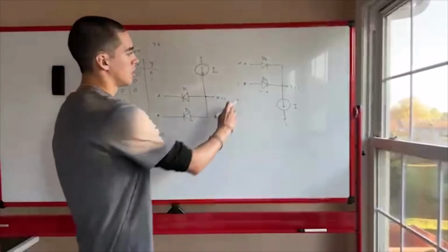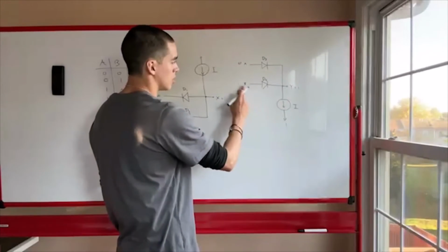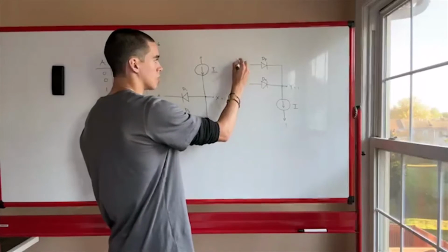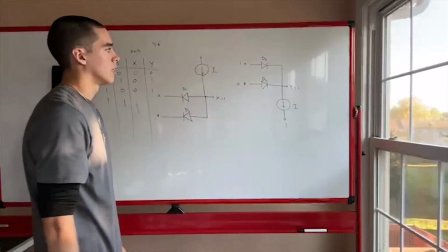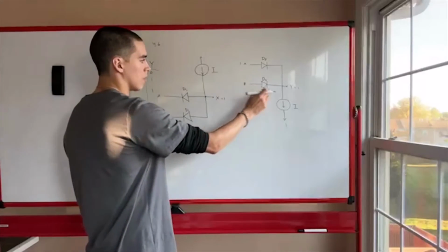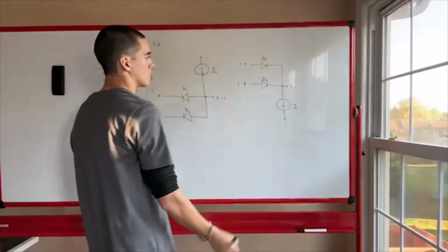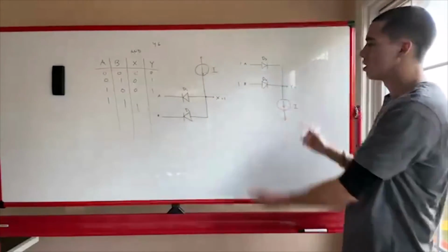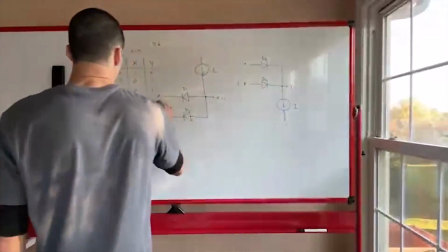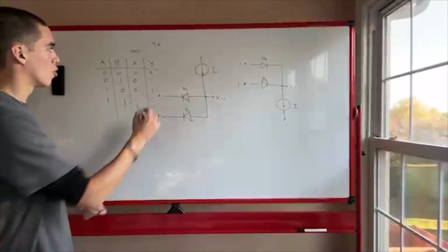And you can see because of the symmetry in the circuit that if you flip this and made this 1 and made this 0, the same thing would happen. And then let's make them both 1. Let's assume this is on, it'll short, so Y would be equal to 1, and then there, done. Alright, ta-da. So this is an OR gate.